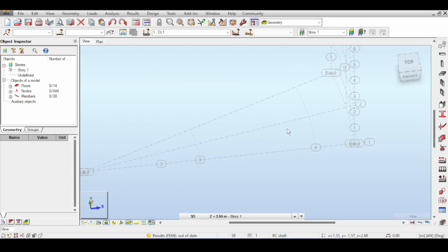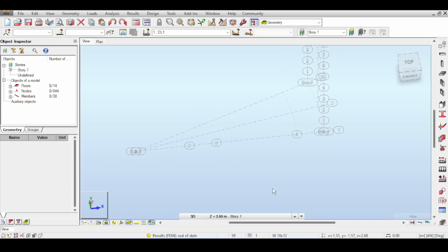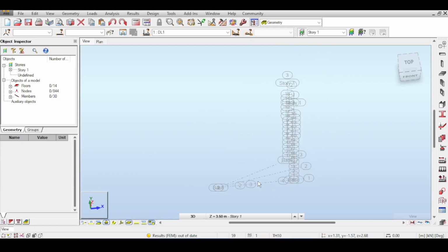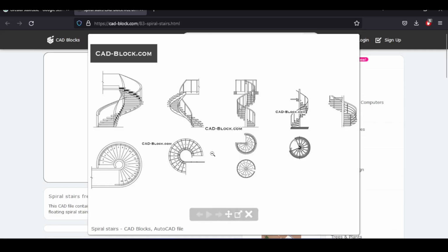The second thing I want to talk about is the cantilever staircase, and the cantilever staircase is connected to a central column. Now, this is gonna be really, really iffy, and I'm totally not a fan of this, to be honest. I'm not a fan of cantilevering your stairs. This works for the smallest of cases, and to be honest, I'm kind of anti this. You need to have at least a support in the middle or somewhere. But still, I mean, okay, let me do this.